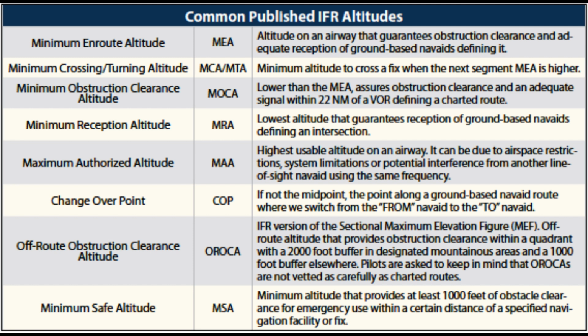Minimum altitude rules are designed to ensure safe vertical separation between the aircraft and the terrain. These minimum altitude rules apply to all IFR flights, whether in IFR or VFR weather conditions, and whether assigned a specific altitude or VFR conditions on top.